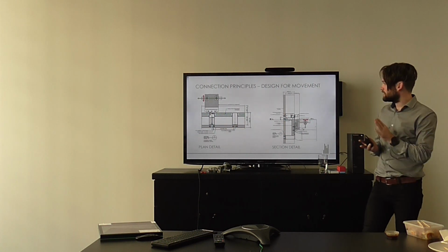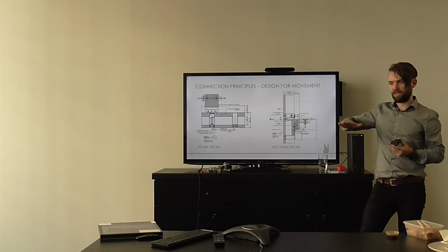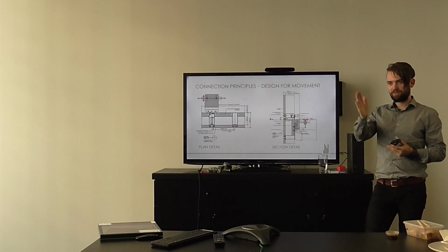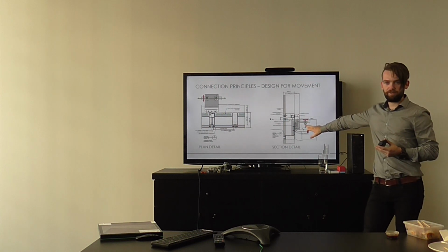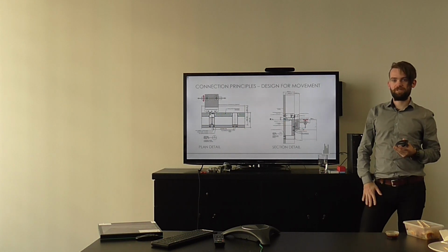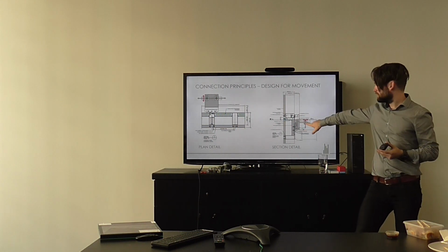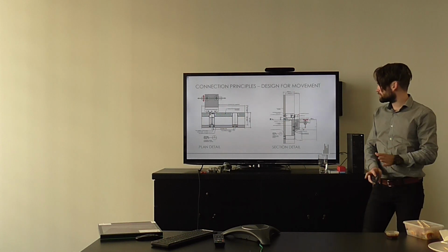The next thing we can do here is we've got some neat slotted holes in our bracket, so we can slide our bracket in and out to make sure that we get our facade to the exact position that we need, as well as lining up with this casting, which will always stay that distance relative from the slab edge. So if the slab edge is way back, this casting will be further back here. So we need to accommodate for that.